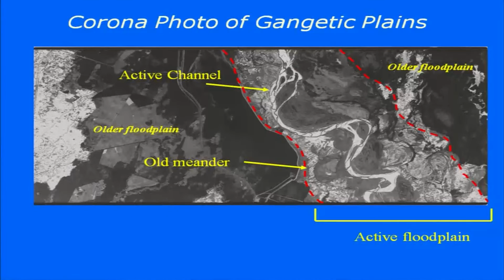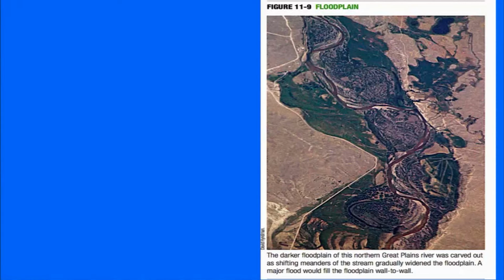So, these are the ways to identify, using high resolution satellite data, the landforms associated with the channels and the boundaries of the older floodplains and the newer floodplains. This is again a similar type of aerial photograph which shows the location of the channel and then the active floodplain. This greenish part is a portion of the active floodplain, and you have the meander scars.